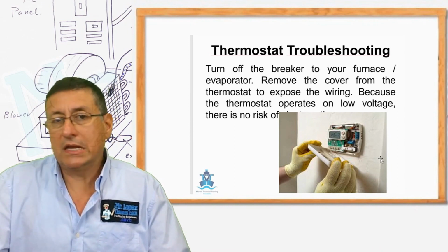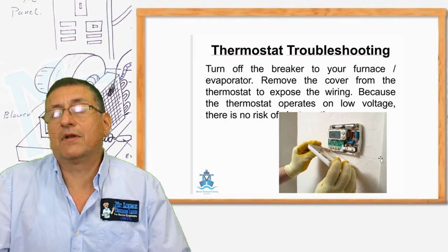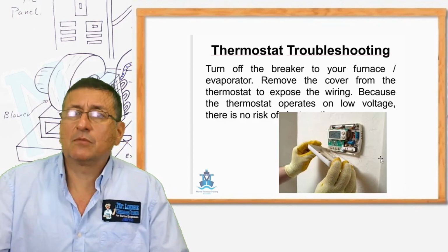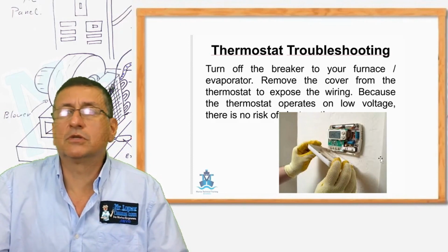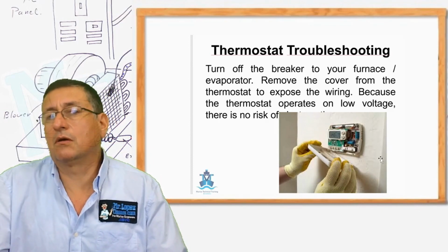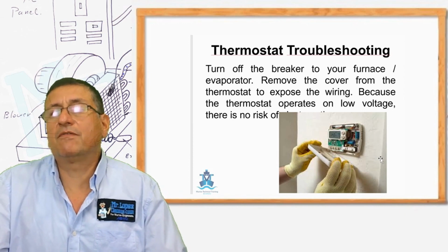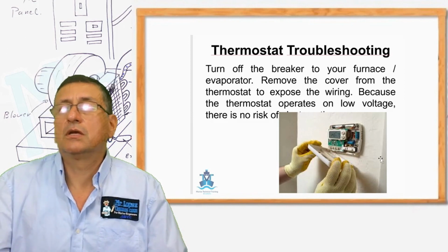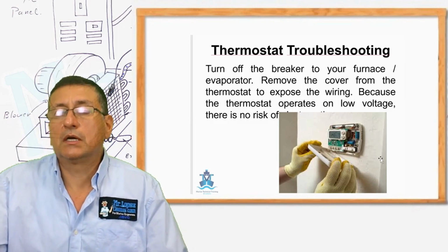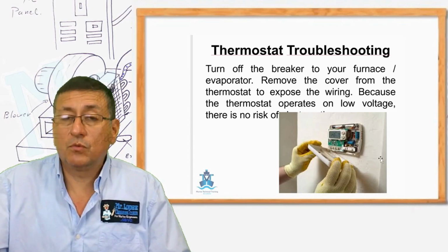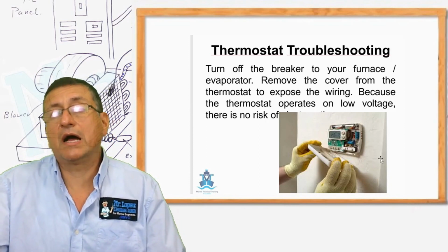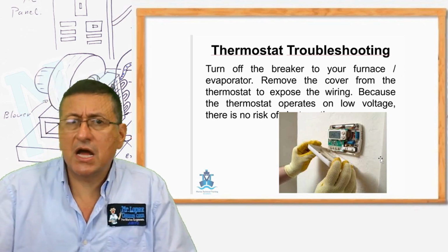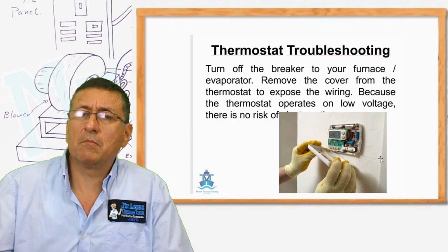Both of them are widely used. You will find in different boats a mechanical or digital thermostat. Can I replace my mechanical thermostat with a digital one? Yes, of course. No problem. The only thing you need to verify is whether the plug is the same plug that you need to introduce in the circuit board, and verify if it's compatible with the unit that you have. Probably ask the manufacturer what type of digital thermostat is compatible with the actual unit with the mechanical thermostat.